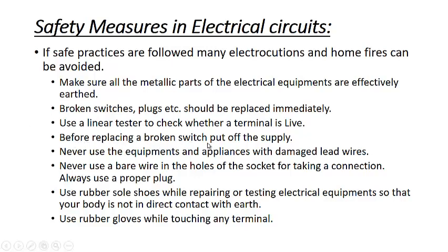Before replacing a broken switch, put off the supply. Irrespective of anything else, if the switch is broken, you should put off the supply before replacing it, because you will avoid any electric shock. Never use equipment and appliances with damaged lead wires. Lead wires should be healthy; they should not be damaged.